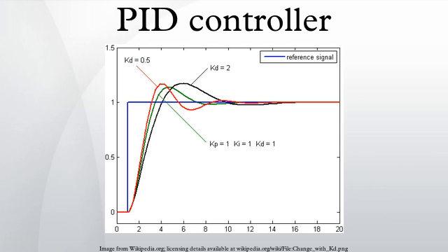On a digital system, the possible proportions are discrete. For example, increments of 0.1 second within a 2-second cycle time yields 20 possible steps, percentage increments of 5%. So there is a discretization error, but for high enough time resolution this yields satisfactory performance.